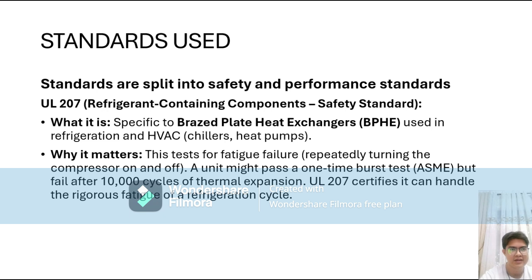So, although used in refrigeration, this standard is still meant for a plate heat exchanger, a braze type, and it shows that if certified under this standard, a plate heat exchanger would be able to operate in real conditions, not only ideal testing conditions.